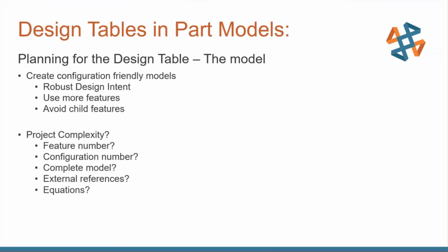And what about equations? That can definitely add to the project complexity. That can help with the automation. Maybe fewer parameters in the design table that you're controlling, more automatic updating within the SolidWorks part model. Again, it can all work together. And of course, those equations can be Excel formulas and Excel equations. Very powerful tool. You can really do some programmatic functionality in your Excel file to really help drive the part.